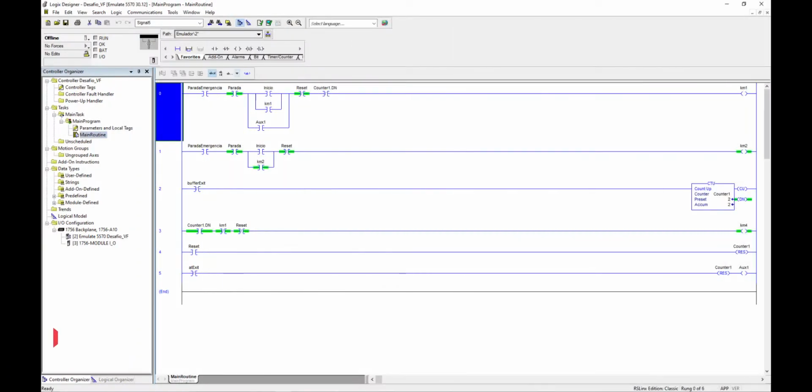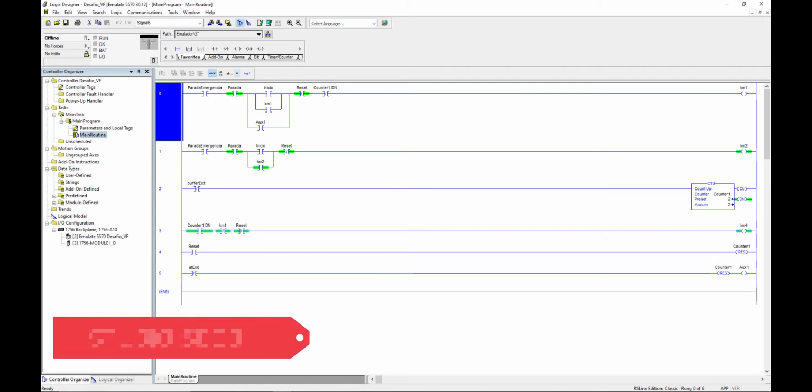The software used for this task is Studio 5000, developed by Rockwell Automation, and Logix 5000 for the emulation of the PLC used. RSLinx was also used for the communication of an OPC server locally, which allows us to communicate with a digital twin of the buffer station via Factory I/O software.